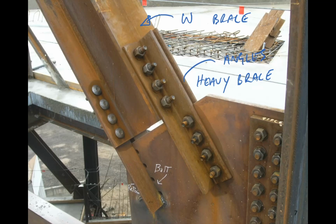And so the tension's coming from the W brace, it's going through shear in the bolts to develop tension in the angles, and then we basically have two tension members or two kinds of elements carrying tension in that kind of situation, and we'd have to look at the tensile resistance of both of those.